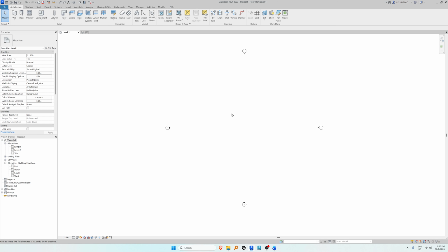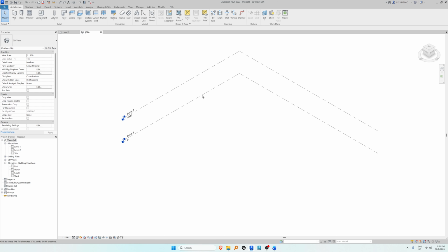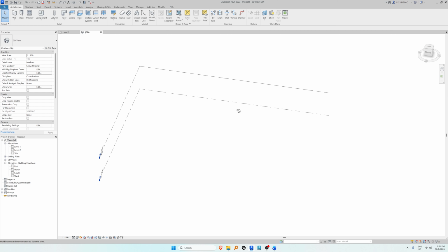These are the controls for standard views like plans, elevations, and sections. For 3D view, it works the same. Hold your middle mouse to pan. Scroll down to zoom out, scroll up to zoom in. And if you want to rotate, you have to hold Shift on your keyboard. Shift, click your middle mouse and hold, and you can rotate around your project.